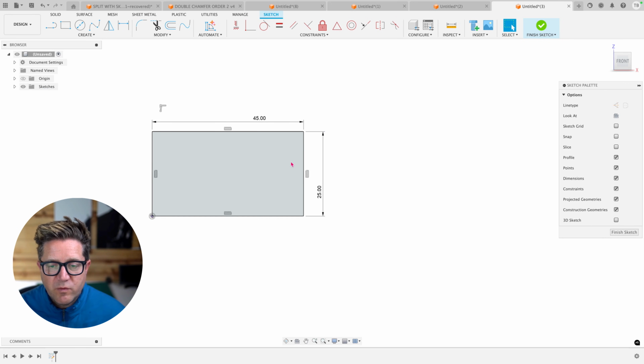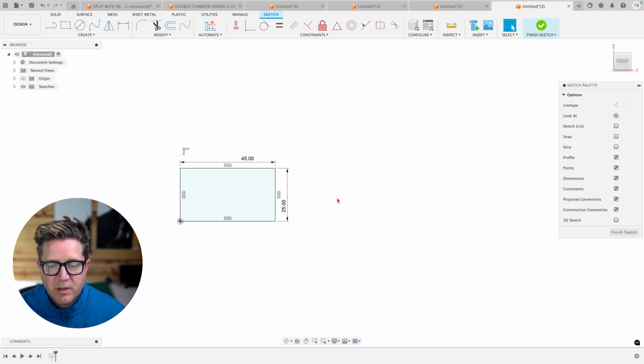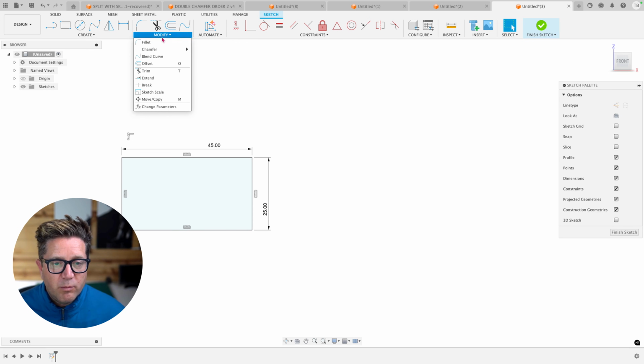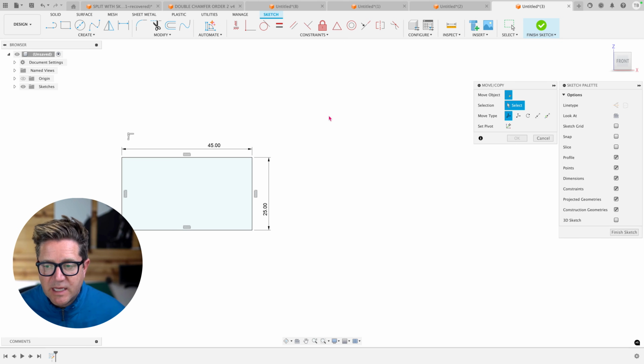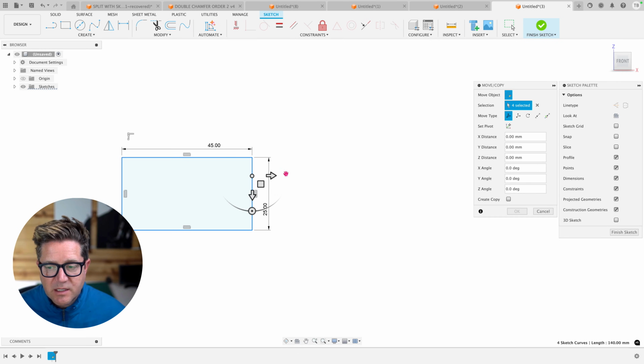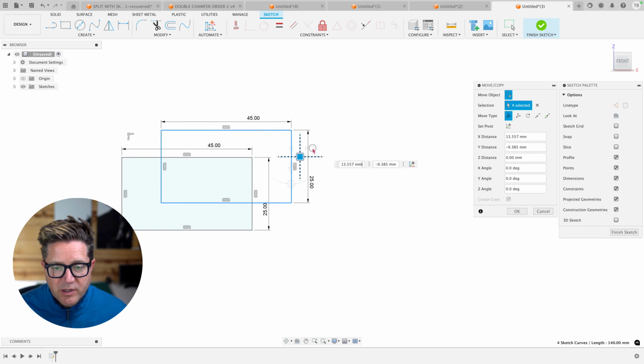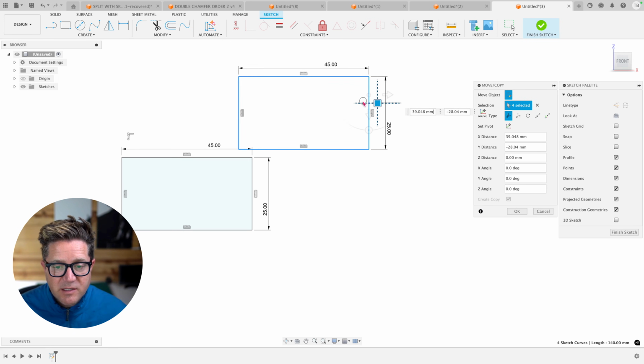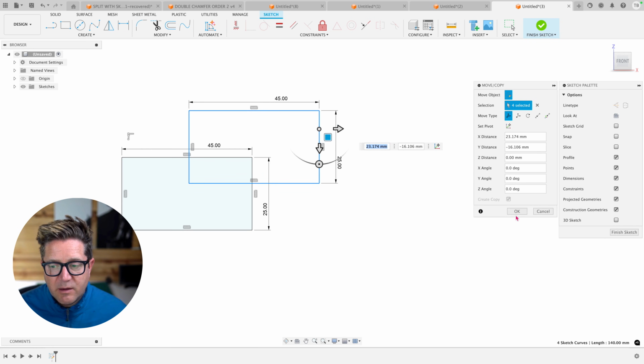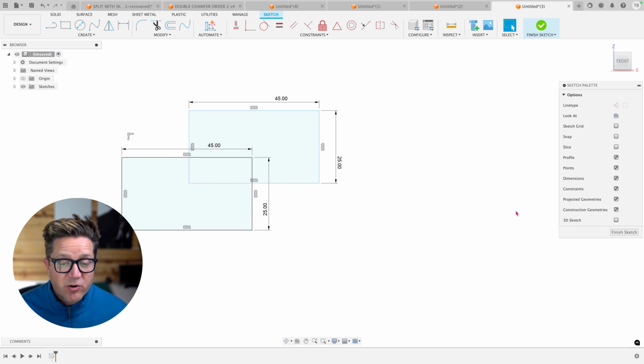If you want to move this and you need this shape, you just need to move it a little bit. Go to move copy like we were just in. Choose the objects. But before you do anything, be careful to come over and choose create copy. This will let you create this copy off in space or move it a little bit, and now you can place it. If it's grayed out, just try again, do another move copy.